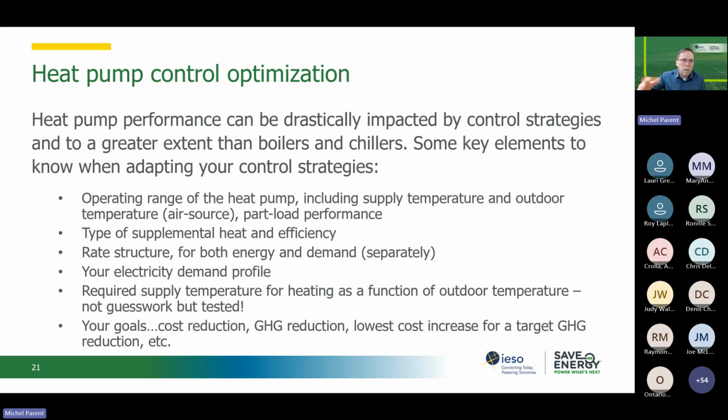Usually that's decided at, let's say, the administrative level of the building. Who decides that? You need to know your rate structure, both for energy and demand. If you evaluate the impact of your heat pump based on an average or blended rate, it is a huge mistake. You never evaluate your heat pumps based on a blended rate, because your heat pumps will save energy but can create an excess demand.